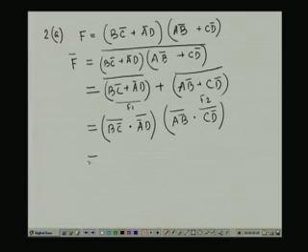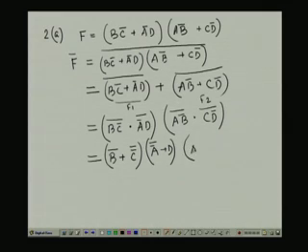Now, we apply the same rule and this becomes B bar plus the complement of C bar, into A bar bar plus D. Similarly, this term becomes A bar plus B bar bar, dot, C bar plus D bar bar.